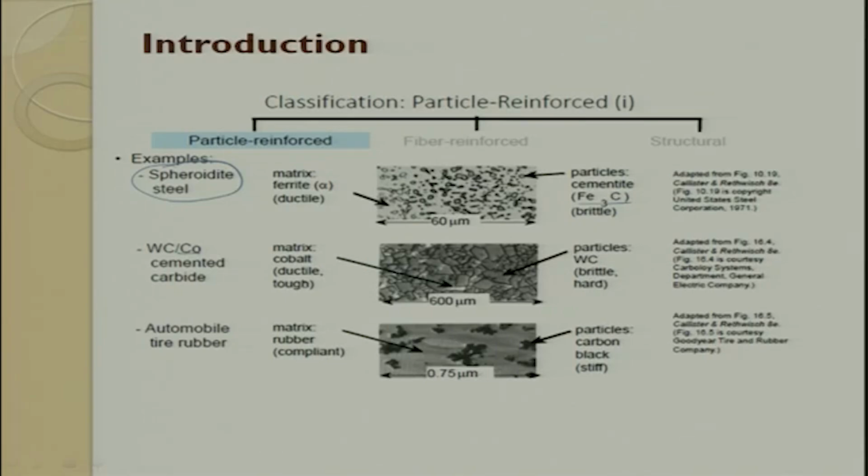Okay. Then a rubber tire is also a composite. So, the matrix is rubber, and then these are particulates of carbon which are getting reinforced for several applications. So, you can see very clearly the matrix, and you can see the reinforcing agent here. The reinforcing agent is quite high. So, the tungsten is quite high. Nowadays this tungsten carbide cobalt, cemented carbide, is a good example for a cutting tool. Nowadays, they are trying to remove the cobalt itself and do sintering completely with tungsten carbide. But you need very high pressure and temperature for doing this. So, these are some of the things.